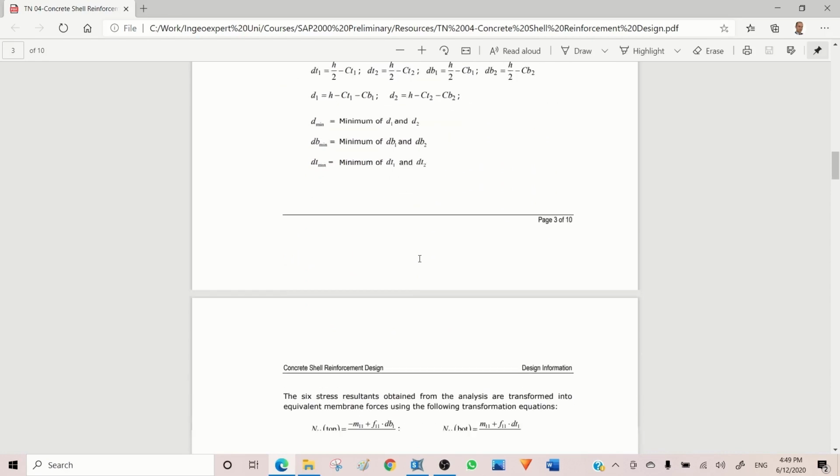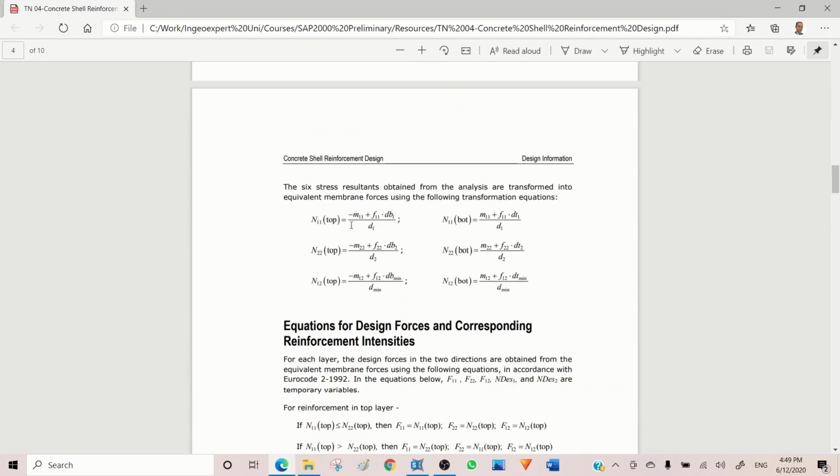So the formulas are here, but after calculating all axial forces and stresses due to moment or due to in-plane axial loads you have, this is generally not what we do when we design a slab or wall. We either consider axial load due to in-plane moment or out-of-plane moment, but SAP adds them up together. So somehow the result of this axial load for design of reinforcement is more accurate when it is done by SAP.